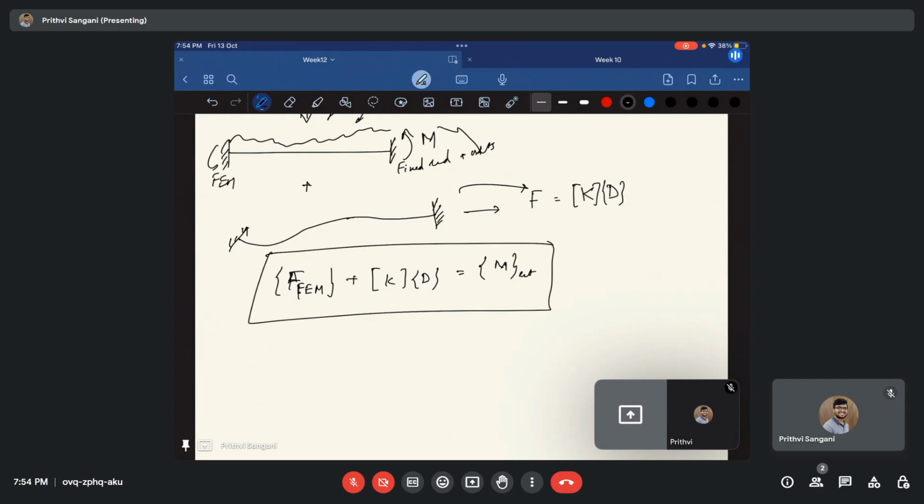In the flexibility method, we make use of compatibility conditions. We find the displacements due to the unit loads, and then we apply the compatibility conditions there. But in this, we find the forces first, and then we check for the compatibility. That is where we draw the results for the redundant forces or the unknown forces.